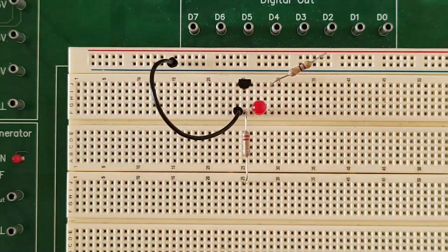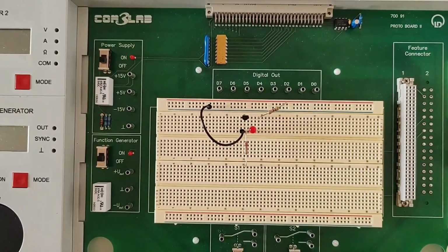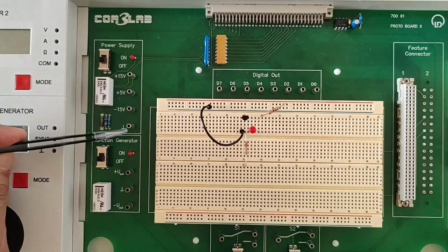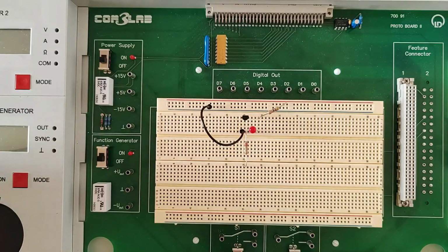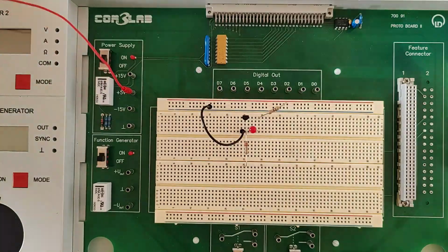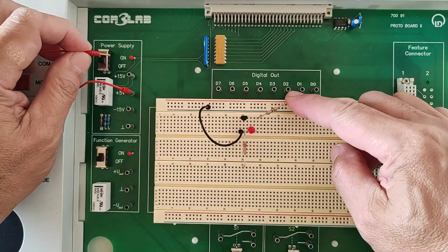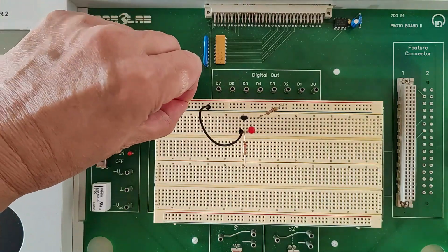I'll connect this one to the out pin, or the output pin, of our function generator. Now, let's connect the power sources, starting with the 5-volt supply. As I said earlier, the 5-volt supply of our power source will be coming here, and the ground of that 5-volt supply will be coming here. So we need to connect power cables coming from these pins. I could use a red wire for the 5-volt source here, and I'll connect it to the top power rail, red side, where this 470 ohm resistor is connected. Like that.